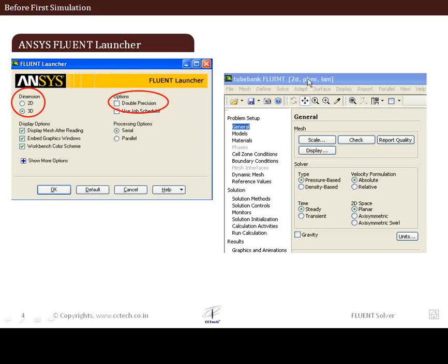Additionally, the next thing that you see here is something about the pressure-based Navier-Stokes equation, PBNS, because the pressure-based option has been chosen. And additionally, it also shows a laminar viscous treatment of the flow phenomena. So if you had chosen one of the turbulence models, if the flow was indeed turbulent, then in that case it will also be reflected at the top.